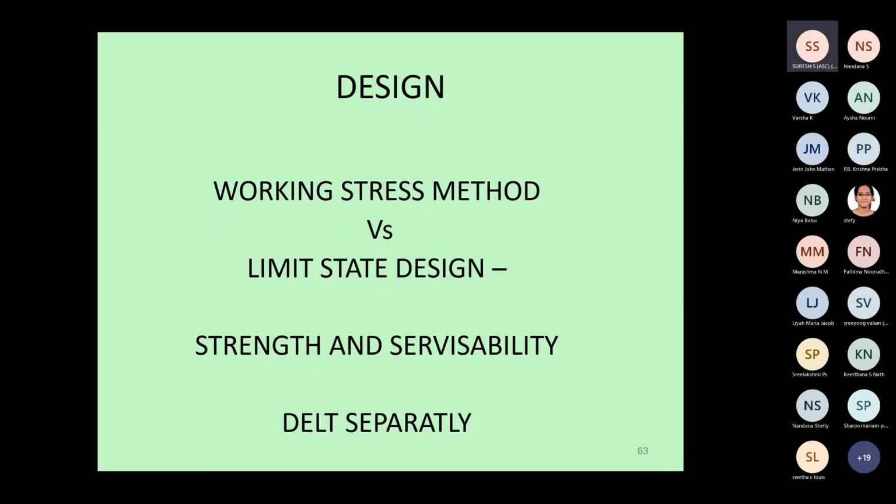This load is converted into a stress and called its characteristic compressive stress or fck. By characteristic compressive stress, we mean if you test 100 cubes, it is this particular value above which 95 tests will fall, and only 5% are expected to fall below.